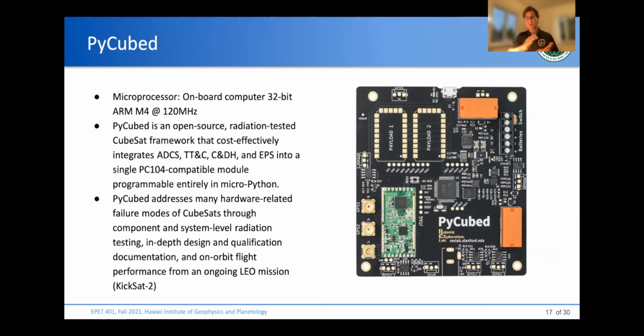Microcontrollers will typically run from dozens of megahertz to maybe 100 or 200 megahertz. Then the microprocessors will be around 100 to 500 megahertz, and then processors will be 500, 600 megahertz up to several gigahertz, like 1 or 2 gigahertz. So the more gigahertz, the more power you're going to be using, but also the faster the computer is in running your instructions.